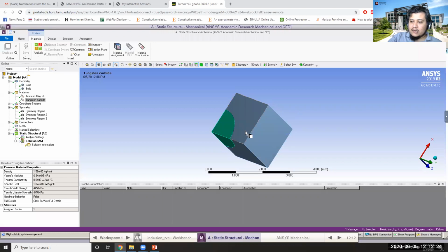So the displacement in the z direction will be enforced at 0. It will not allow any kind of displacement in the z direction. The rotations about the x and y axes are constrained to be 0 as well. Only the motion in the y and x direction can happen, and the rotation about the z axis can happen.